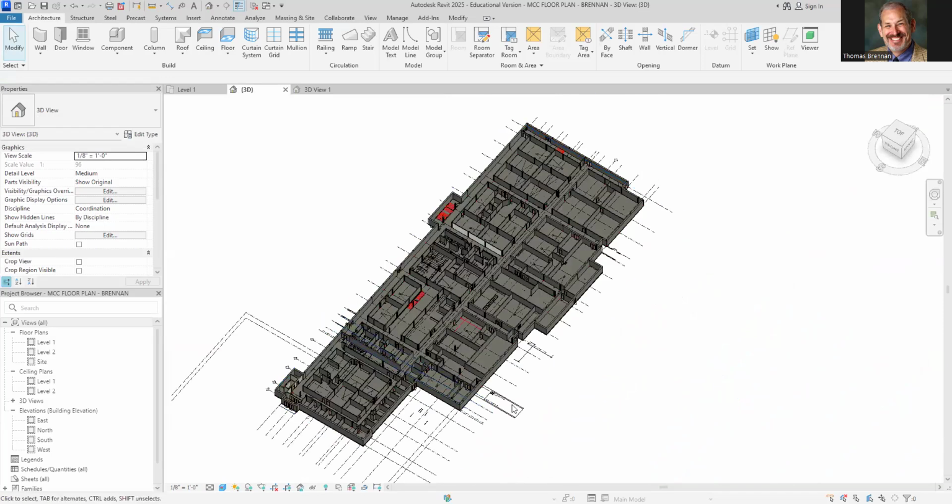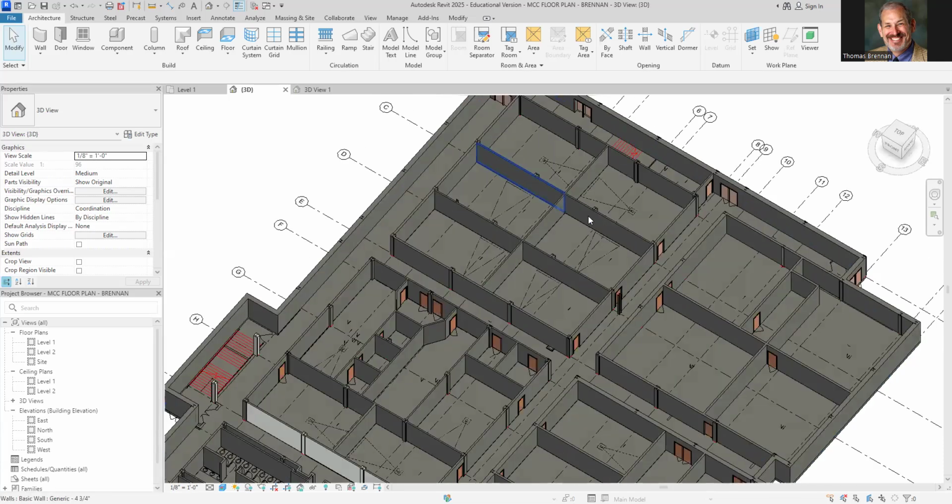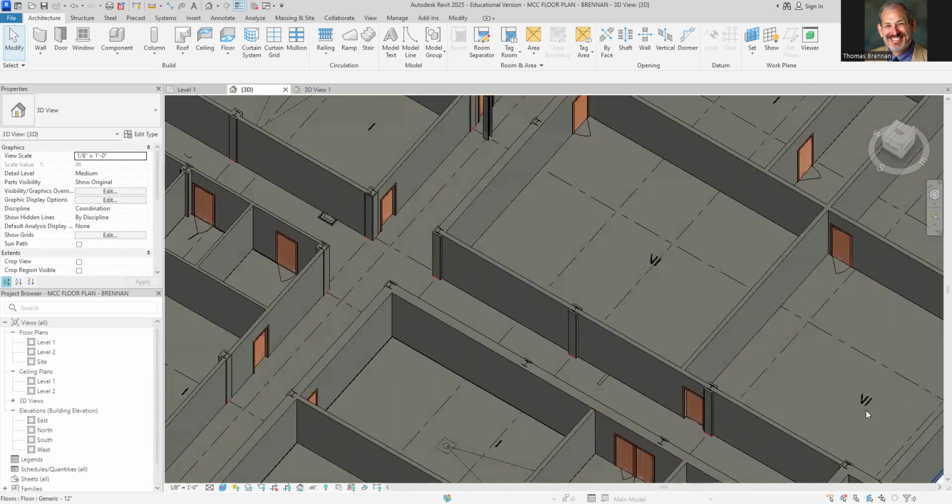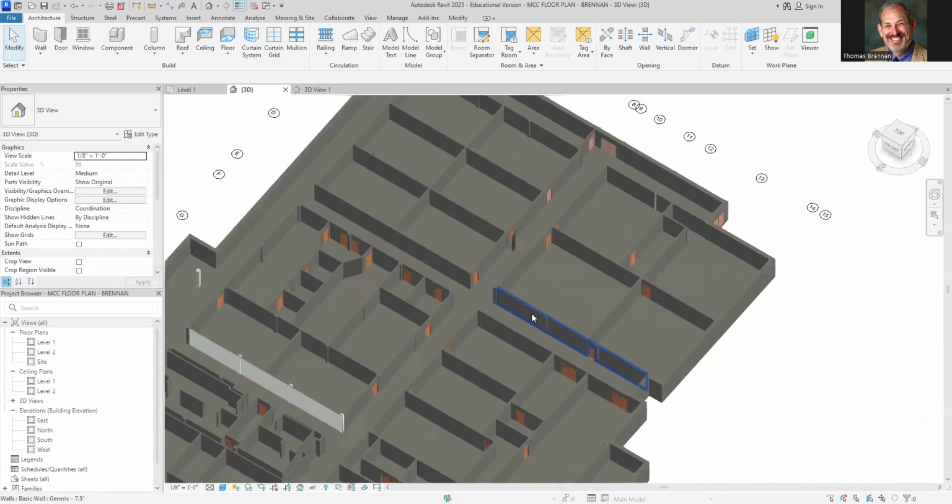Yeah, if it's giving you errors, that means that the actual floor boundary is not in a closed loop, and Revit will never put up with that. So you have to do that yourself. You want us to delete the random columns or just leave them? Yeah, make sure that they're random when you look at them, and then just delete them, because I think a couple were in these rooms here. You can just delete those.